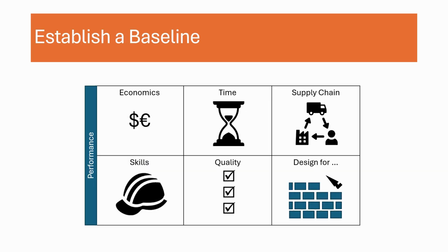We need to establish a baseline for discussing the different processes. The economics are a key consideration, and it's not just the economics for the machine, but the economics with respect to the area of preparation. There could be some unique safety issues or material handling issues. The time element is not just associated with the process planning, because that's one of the beauties of this process family, is the fact that you make very few decisions at the process planning stage and hit the button and go, but there is time that's associated with the actual fabrication process and the post-processing.